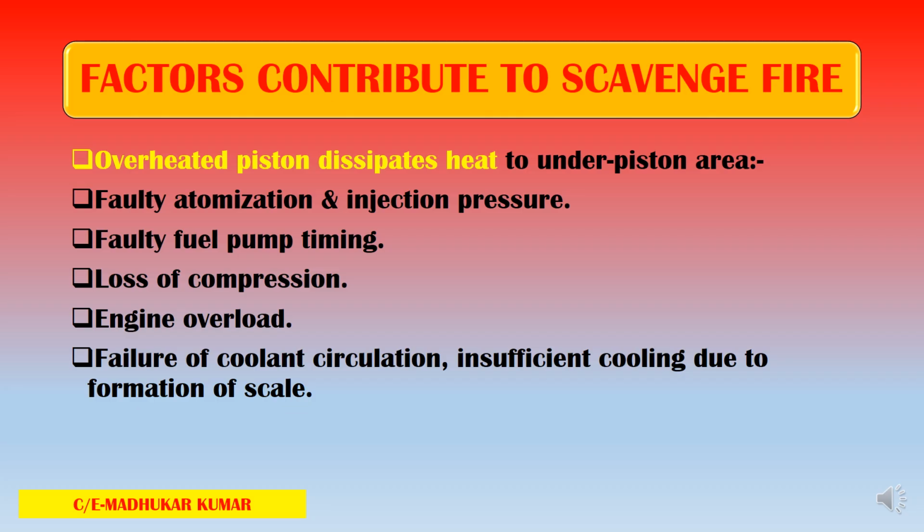Loss of compression: if the piston ring is not proper, there is loss of compression. Engine overload: due to certain conditions the engine is overloaded, which is going to cause overheating of the piston. That is one of the main causes. Failure of coolant circulation, or insufficient cooling due to the formation of scale. Basically, whatever heat energy is developed in the main engine or any engine has to be taken away by the coolants, either the lube oil or the cooling water.